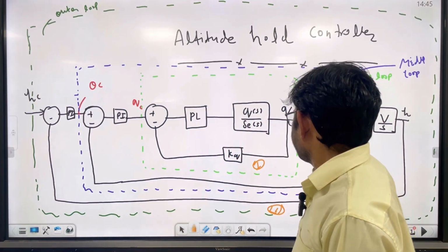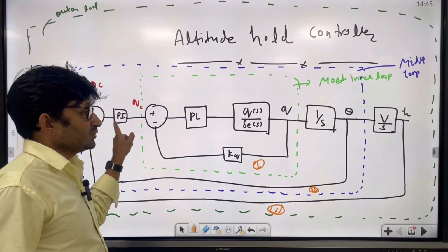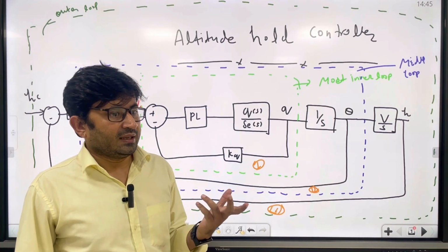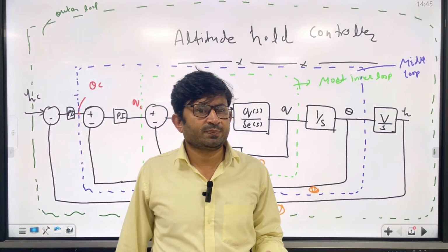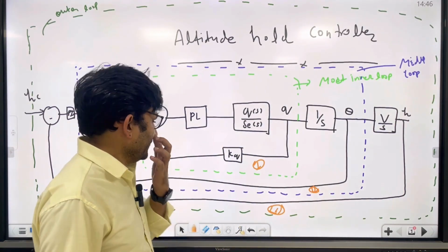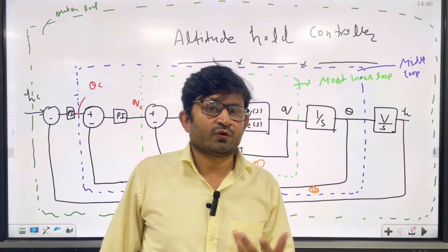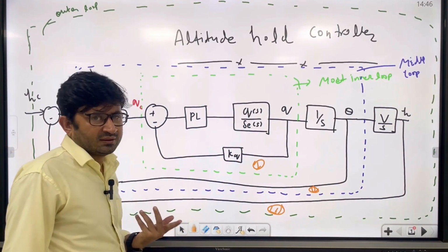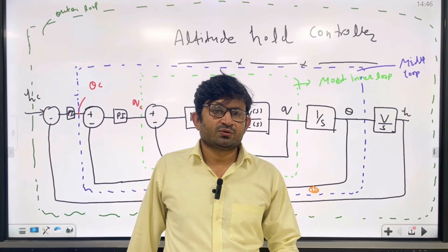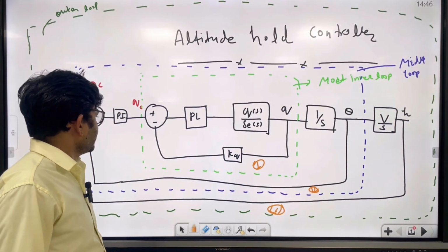Okay. All right. So see, this is a PI I am using. P means proportional, I means integral. I have already explained to you how to select the gain using the Ziegler-Nichols method. You just select P, and there is one way to select I: just select the P value, and from the P value you can find out the I value, which is approximately, or you can just put 5 to 30%.